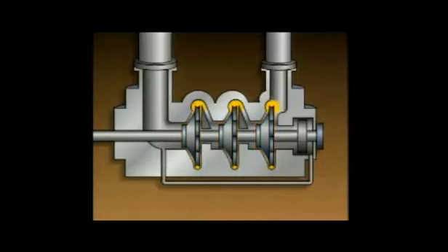Each stage of the pump has its own volute. In the volute, the fast-moving liquid slows down and its pressure increases. Each of the first two volutes discharges into the suction eye of the stage that follows it. The third stage volute discharges into the pump's outlet.